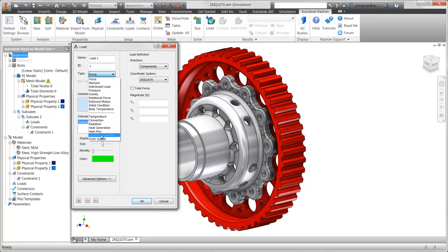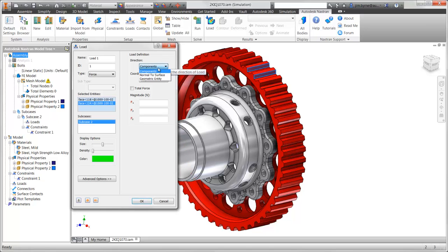There are several ways to apply the load. Use options such as force, pressure, moment, gravity, centrifugal force, and prescribed displacement. There are also loading conditions for thermal studies such as heat power or prescribed temperatures. These loads can also be described with variable distribution for hydrostatic scenarios or bearing loads.